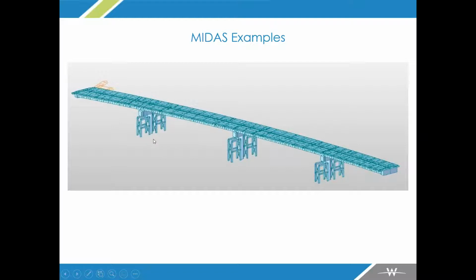One of the big things here that's useful in MIDAS is that you can do your checks on not just the composite girder, but also on the reinforced concrete section standalone, and on the steel standalone section, all within the single model. So you're not going to different modeling software or taking that out into other sources, spreadsheets, calculations. It can all be done within the one model. And that load rating is the same way. So that's very useful and very nice.